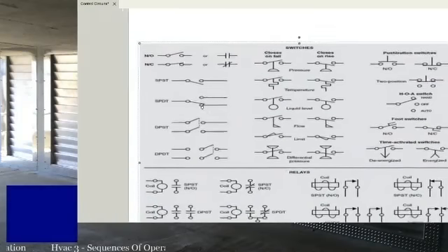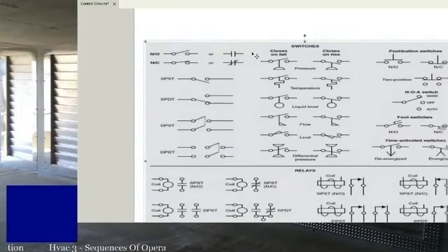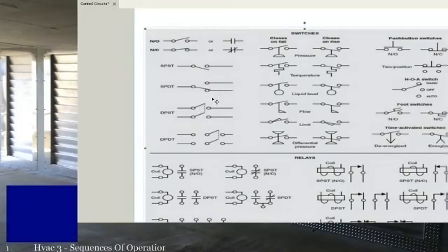Over here, you got normally open, normally closed switches, or the other way to show normally open, normally closed switches. You got single pole, single throw, so it's just on off. Single pole, double throw, so it's on or on the other side. And sometimes things will be labeled single pole double throw if it's got an off position also. Sometimes it'll be labeled single pole triple throw if it's got on or an off position. That's getting a little deep, but